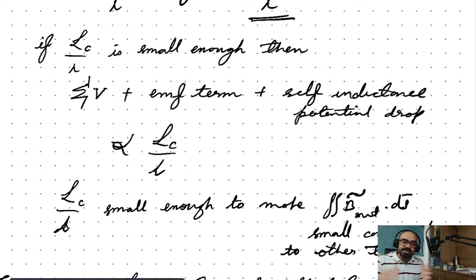Imagine you have a physical system, and you want to create a circuit representation of that system. You need to ensure a few things. First, of course, you need to calculate all the component values, the inductance, the resistance, and so on. But more importantly, you need to make sure that your circuit has loops whose circumference is smaller than lambda.